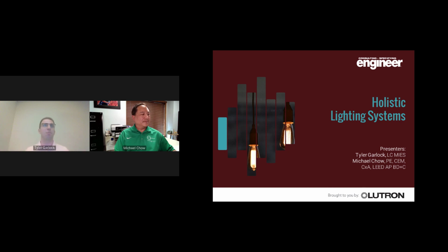For me personally, I prefer 3,500 Kelvin because it is a little bit warmer and a little bit more pleasant to be in. I find 4,000 or 4,100 Kelvin to be a little bit too blue and harsh on my eyes, but it is very much personal preference. So whether it's better or worse, not for me to say. You've got to talk with your owner, and if it's an existing company, figure out what they have in other buildings. That way you're not creating a shock to the system when they move into their new building, and that sort of thing.